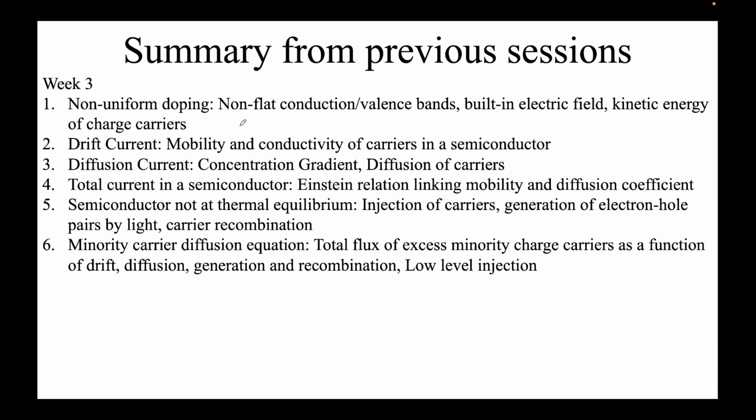Finally, we saw that the doping need not be uniform, and so what we saw is the peculiarity that we can have sloping bands. If you have sloping bands, please remember this is potential energy. When you have a gradient of potential energy, this is electric field, you know, it's minus grad V. So sloping bands will always have an inherent, built-in electric field.